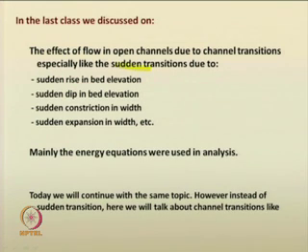The sudden transition, how due to the sudden transition in the channel, the flow is getting affected. The sudden transitions that were dealt with were sudden rise in bed elevation, sudden dip in bed elevation, sudden constriction in width, sudden expansion in width. So, these four cases we had elaborately studied in the last class. We have mainly used the energy equations to analyze these things.